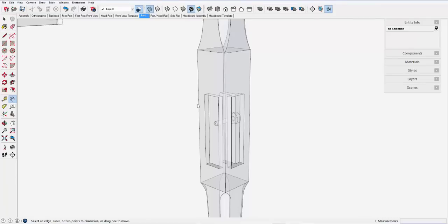Okay, so detailed dimensions like the distance up from the square section, the base of the square section, so I can now in the shop precisely locate these sockets, these recesses, and precisely locate where to drill for the bed bolt on the drill press.